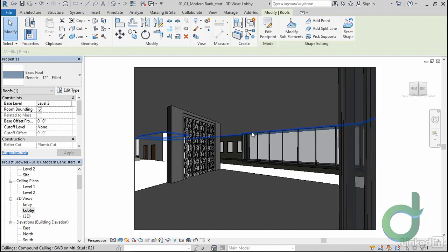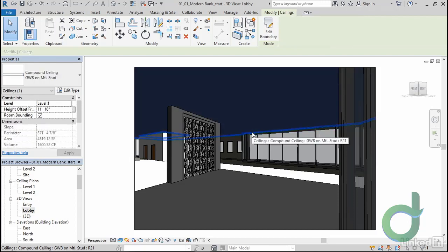This ceiling may be problematic though, as there's a lot of places in this ceiling, and like objects, where I've got multiple lighting conditions that are going to try to hit one mesh. Additionally, we'll be punching some holes in with recessed can lights, and that in itself gets problematic in a large mesh, because we get long, thin triangles when we export this over to 3ds Max, and those can lead to rendering artifacts.